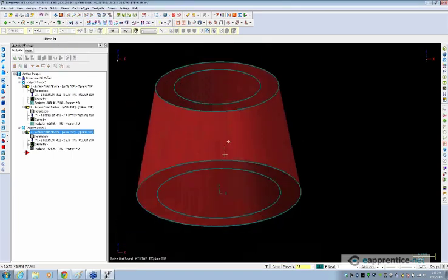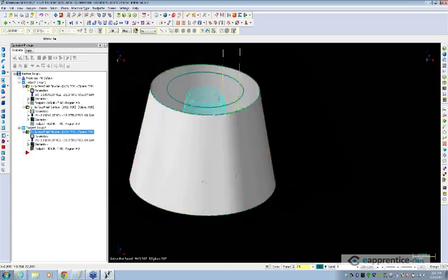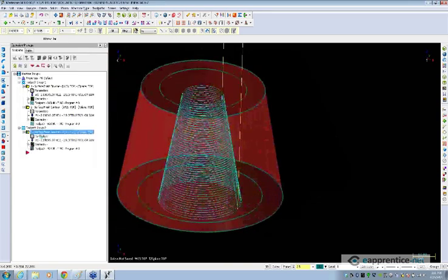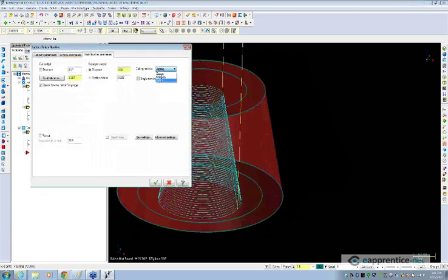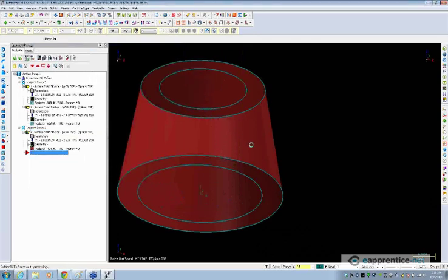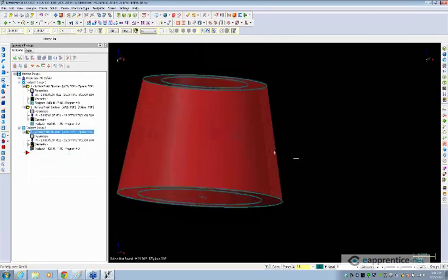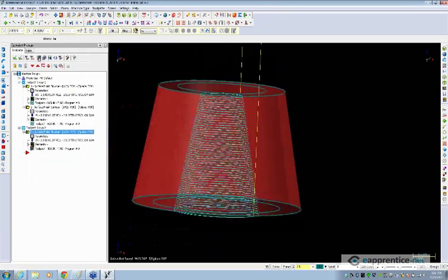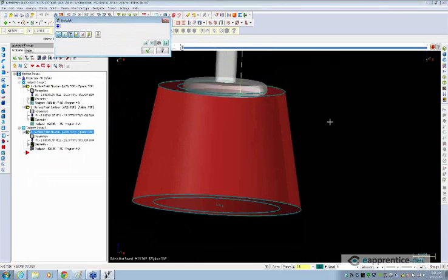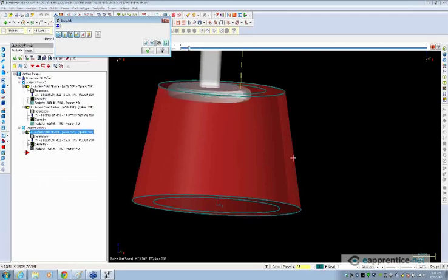There's one more thing that I think we can clean up here before we adjust the lead in and lead out. In addition to zigzag, we also have the option for spiral in flowline. So if you're doing a single surface, this spiral is going to produce some really nice motion. So when we set it to spiral instead of zigzag or one way, now we get this nice smooth toolpath that just does this constant, almost ramping motion as it goes down this surface.